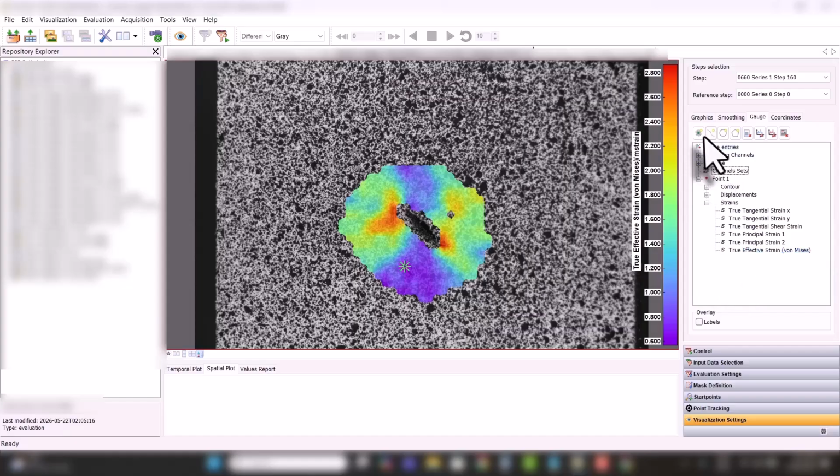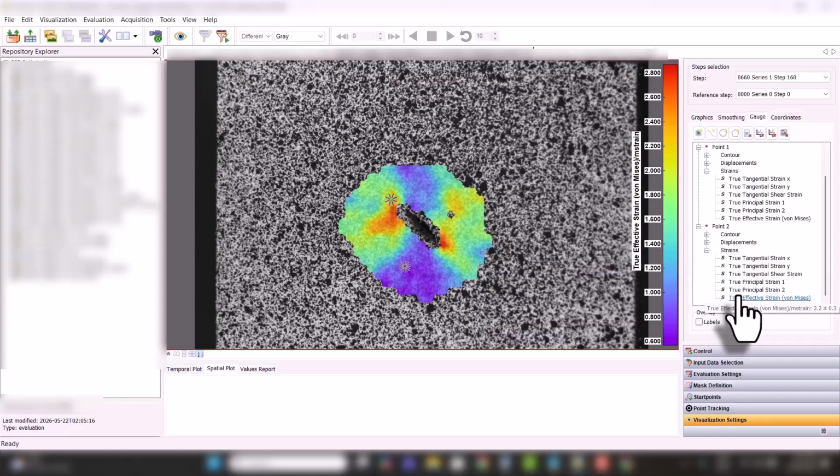So this has a precision of 0.2 millistrain. This has a precision of 0.3. So that's something you can work with. That's well into the elastic region. And so the idea is with the MATLAB code, most of this would be getting thrown out because it overlaps with the original correlation, but you'd have all this data in here would get added on to the previous correlation.